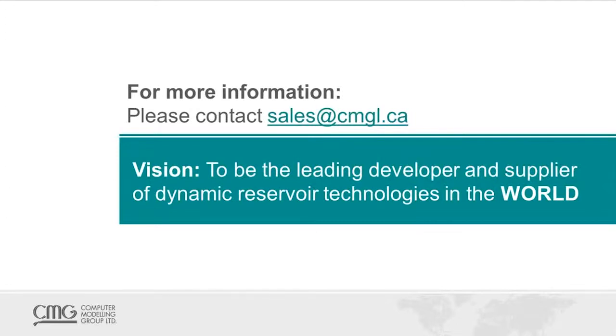What is suggested is that if you are using the pseudo-miscible model for carbon dioxide injection, take one or a few cases from the pseudo-miscible model and then run them under compositional simulation to see whether the results are matching or not. The main issue is that sometimes during compositional simulation, we have too much composition variation in the oil because of the pressure or the composition variation. Because of that, maybe you cannot use the pseudo-miscible method for carbon dioxide injection in the black oil model.